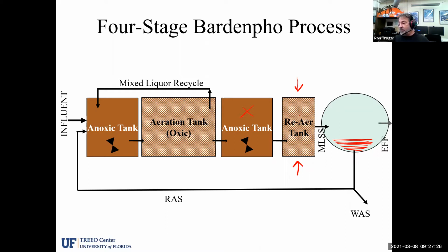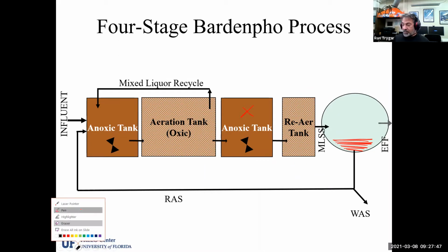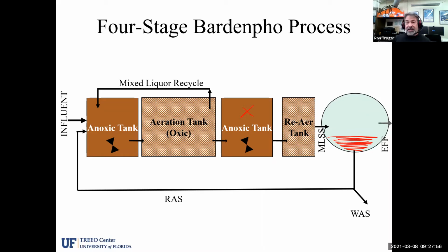So the dissolved oxygen or the amount of aeration isn't quite as critical in this re-aeration tank. It just needs to be aerated so that it's getting some dissolved oxygen, but also shaking up that mixed liquor so that we're getting the actual nitrogen gas coming out of the floc, which helps the clarifier settle a little bit better. By having those bound gases released, the floc tends to settle better. So it improves the settling in the clarifiers.